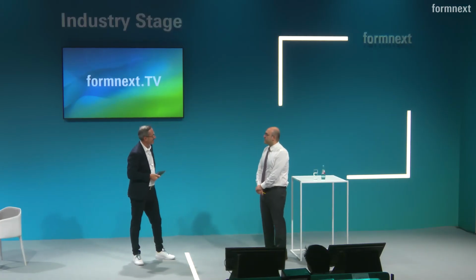That's actually a very good question. We are achieving that at Oak Ridge. These high quality CT data give us very high quality data for in situ monitoring. So we use them as a ground truth for in situ monitoring to improve our in situ monitoring process. Once we improve it to get to a good detection capability, then we can get rid of CT and use that as our process. And in a paper we recently published, we showed that we can detect 90% of defects in situ with more than 200 micron or so. So that's what we are working on.